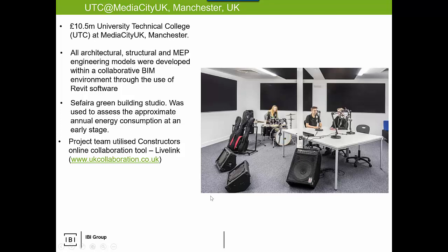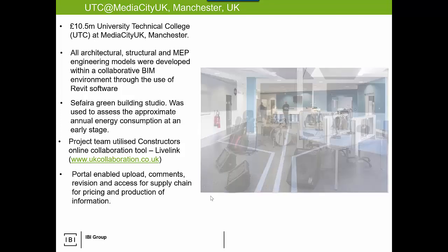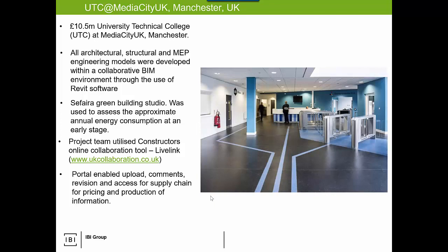So they used the LiveLink tool as well to help connect with the constructors. And this is an important concept because the UK was really at the forefront of what they call a common data environment, which is basically a common access point for consistent, accurate, and valid information. In the world of BIM, I talked in a collaboration session about WIP, shared and published.